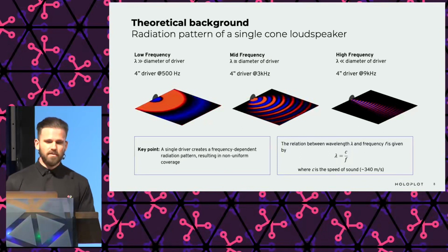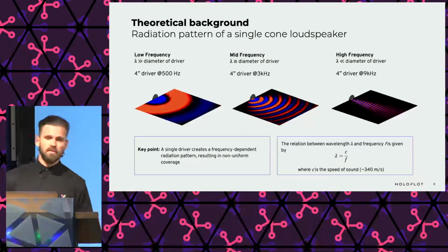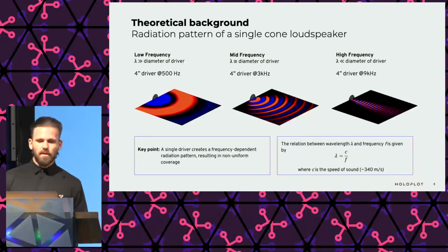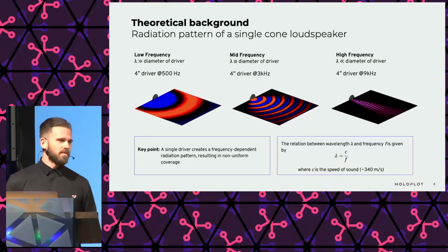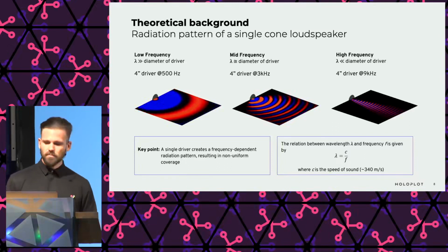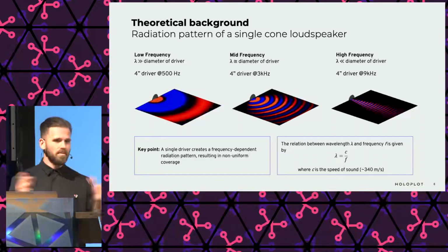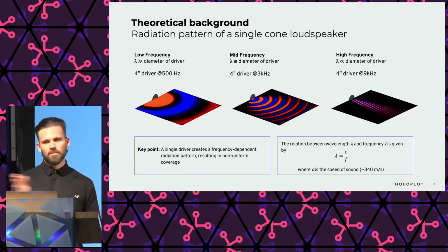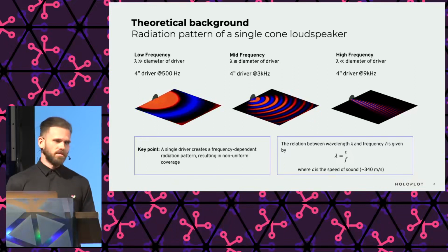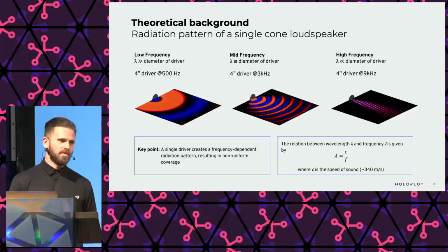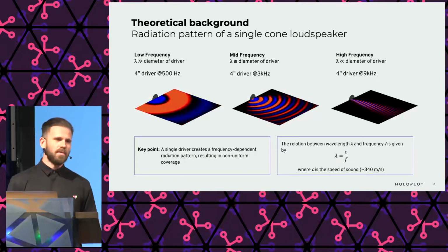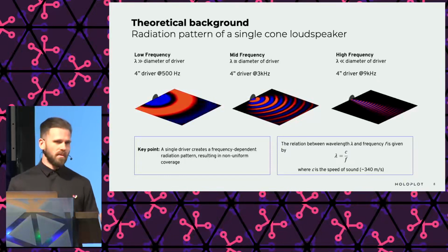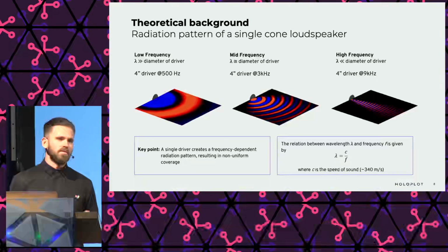As a summary from this slide, one could say that the loudspeaker has a directivity pattern that looks different for all different frequencies. As a consequence, the beam, or the sound field, or the coverage for that loudspeaker will look different depending on the direction from which you are listening to that loudspeaker. If you are on axis, listening right in front of the loudspeaker, you will hear all frequencies with more or less the same level. But if you move sideways, you will experience different levels between the low frequencies and the high frequencies.